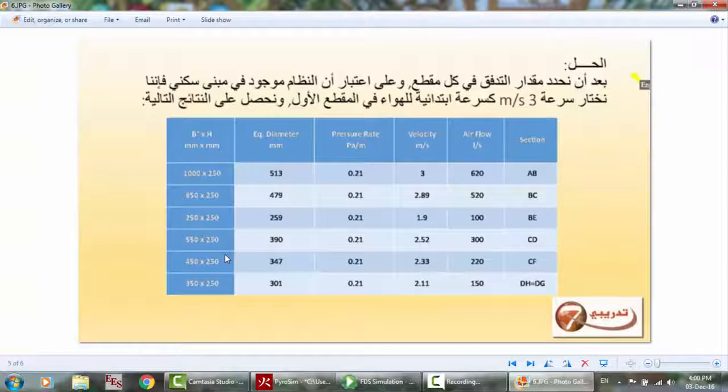You have to follow the best for your design. You may change both, no problem. But the very important thing is to get an aspect ratio that does not exceed 4:1 or 3:1 in residential or offices, not in industrial applications. Industrial applications may reach 12:1 or something like that.